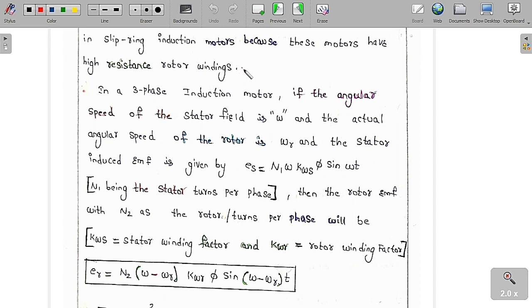I already told you crawling is nothing but, so basically what is crawling? Crawling is when the motor thinks that whenever the rotor speed is nearly equal to Ns by 7, it is a stable region, but actually it is not because of the harmonics of the flux which is present in the air gap. The main reason for this is the slots. The slots in the stator and the rotor are going to distort the flux in the air gap. So because of this non-circular flux, we are going to get the harmonics. In that, the seventh harmonic is more dominant.